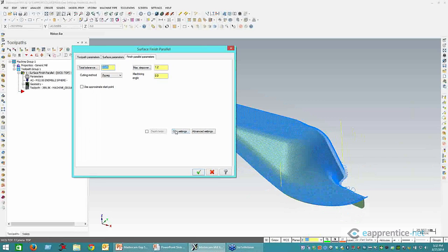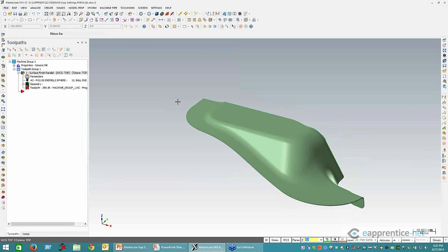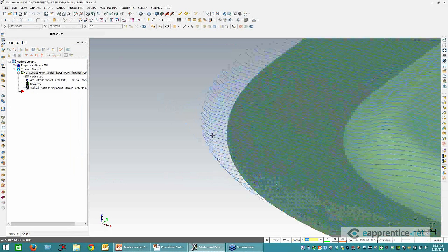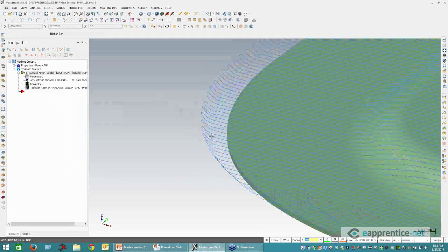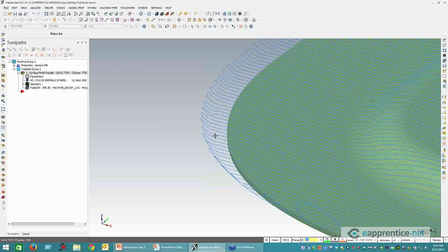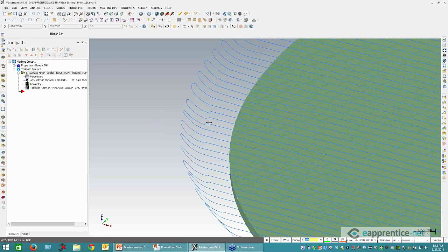So right now we're using a 90-degree tangent arc angle. Let's change that to 45. And instead of doing a full loop up in a 90-degree motion, now we come out with our line and we only complete about a 1/8 of a circle before we move over with the smooth and move back down to the start of the next slice. Again, if it has trouble calculating that tangency, it will default to broken.